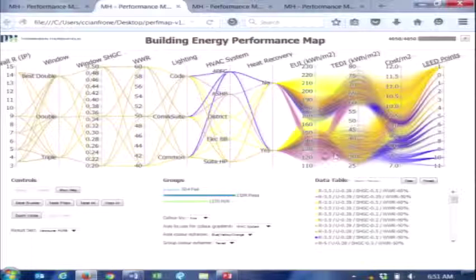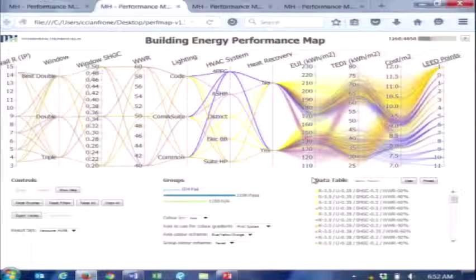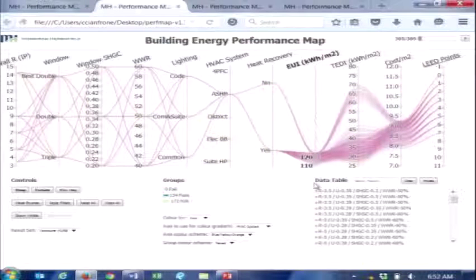Is it energy use intensity? Is it thermal energy demand? The City of Vancouver is actually struggling with what is the right metric to drive the outcomes we want, which is low GHG emissions and long-lasting, durable buildings that have really good building envelopes. It turns out that they thought it was energy use intensity, but to get a really low energy use intensity, you could just use a heat pump, and you're fine. You get low energy use intensity.